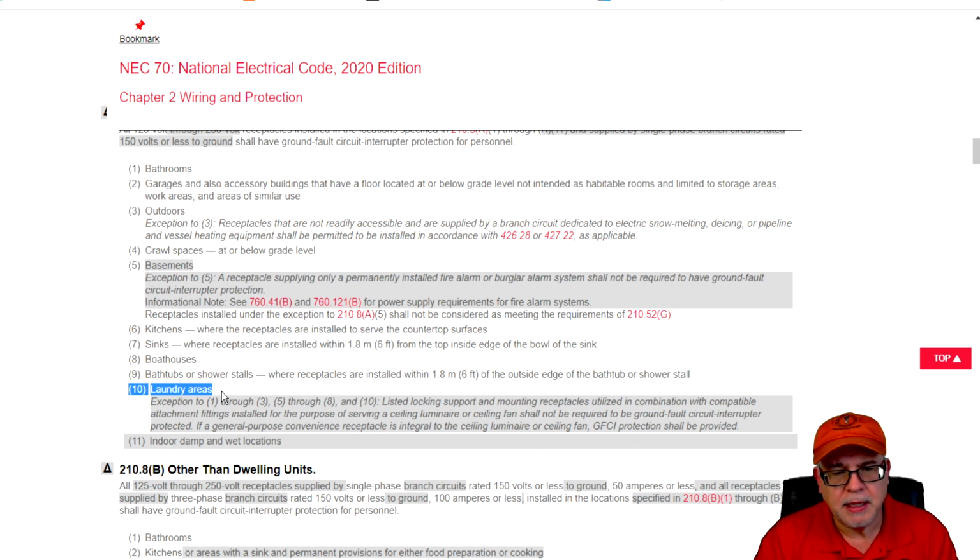If it trips a GFCI, typically it means we have an appliance or a piece of equipment that's leaking more current than it should be. So the GFCI is functioning as it should, and there's a problem that needs to be addressed. Granted, we're getting a lot of expansion of GFCI devices, and I don't see them stopping anytime soon. They do save lives, and they are cheap insurance, if you will. So I have no problem with their expansion.